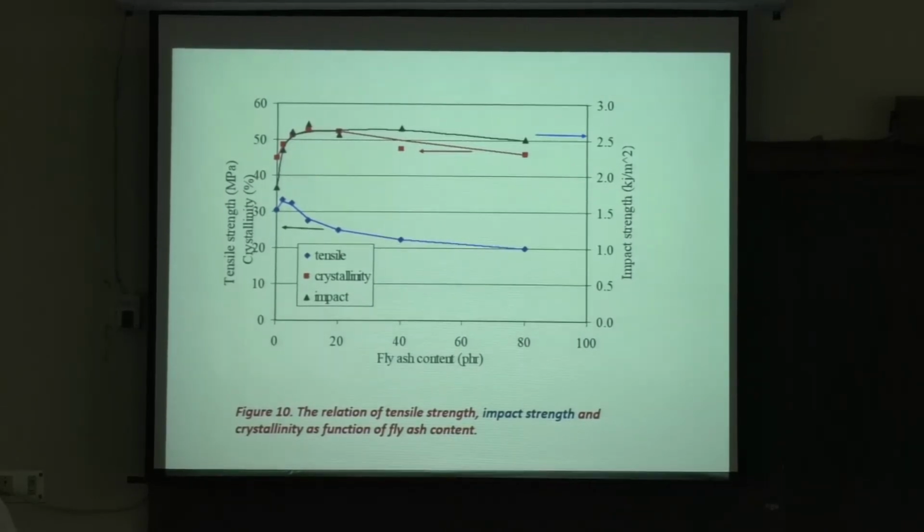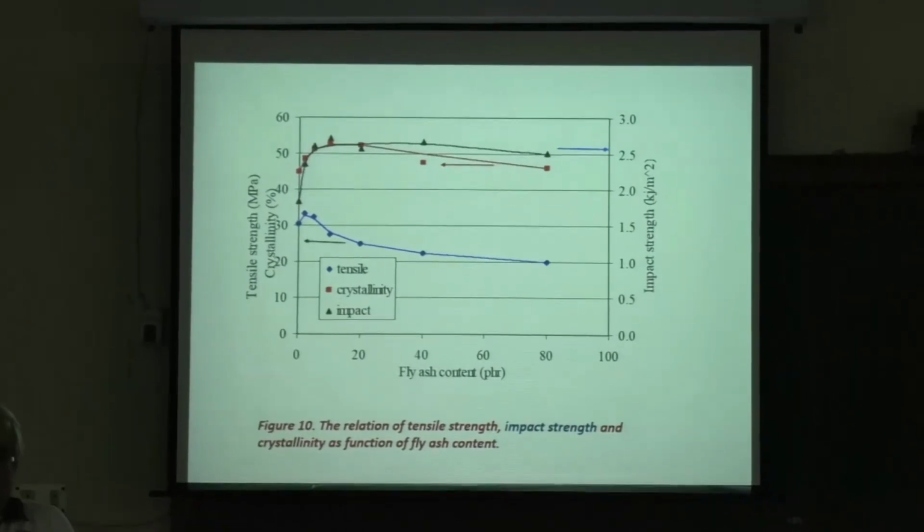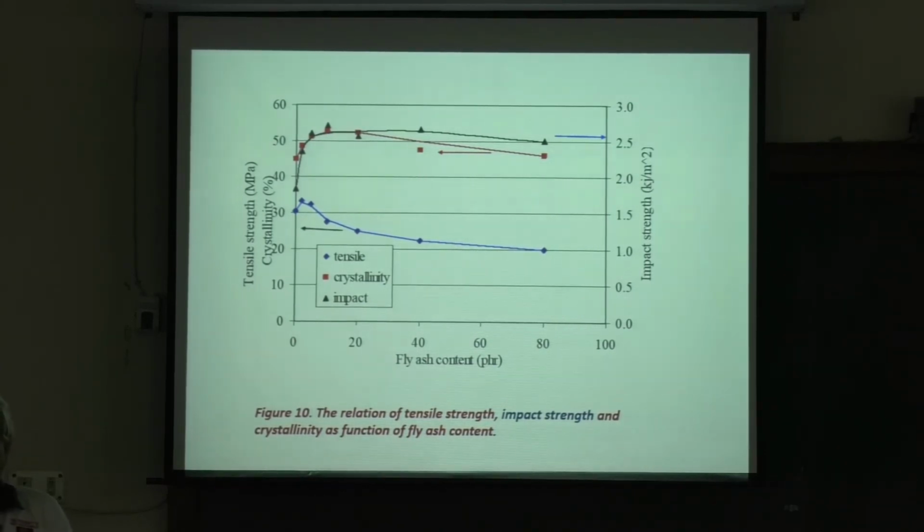And impact properties are very important and often the most important. And in many situations, tensile stress shows certain things, but tensile stress also can generate this localized stress intensity factor. That's why instead of tensile stress, even if you use low speed fracture toughness test, that is better than tensile stress, particularly for composites. If it's a single material, if you have only polypropylene, polyethylene and things like that, you can use tensile.